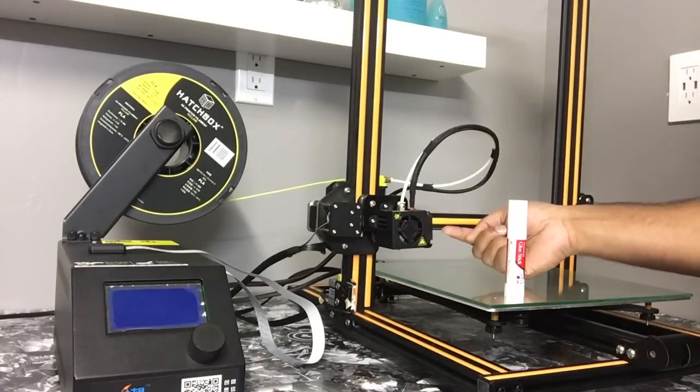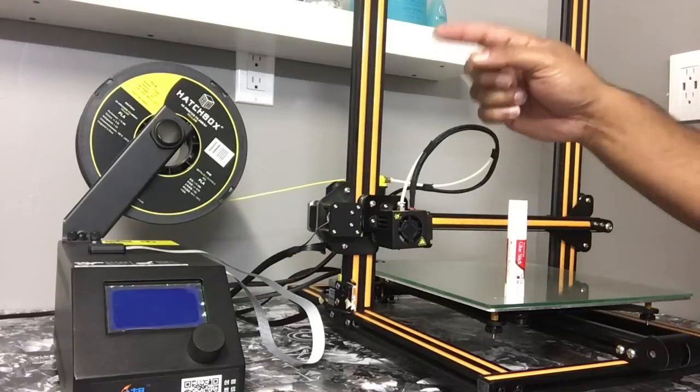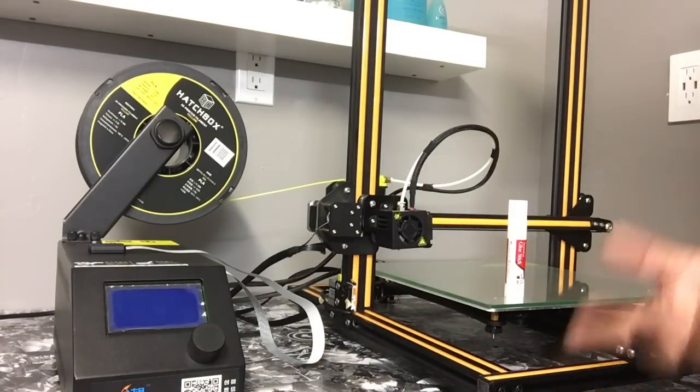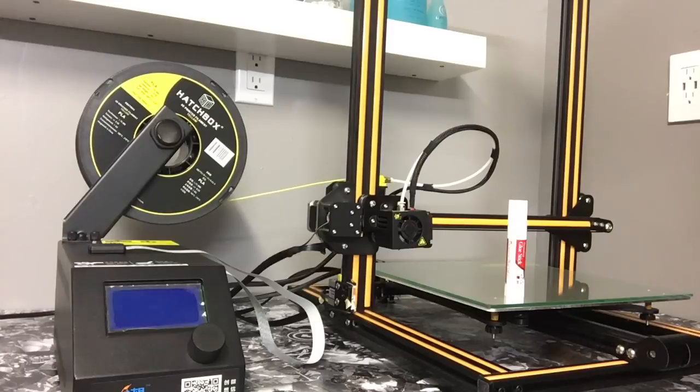The fan on the side will only turn on if it is written in your G code and told to turn on. And that is like a slicing thing, depending on what program you're using. You can set the parameters for that. Basically, it'll tell you like turn off fan after 4th layer or 3rd layer. You can have it always on, or you can just do 5th layer, 1st layer, basically whatever you want. So that's just in the slicing program that you can adjust yourself and go from there.